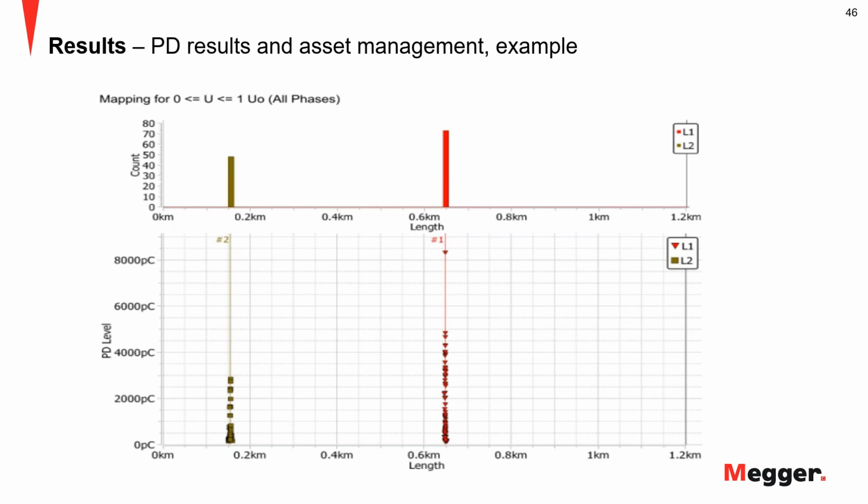And around 2,000 feet, you got a second set of data, in this case measured on A phase. And the highest data point was more than 8,000 picocoulomb. And most data points reached 3,000, 4,000, even 5,000 there. So this is significant. This is a very high number.